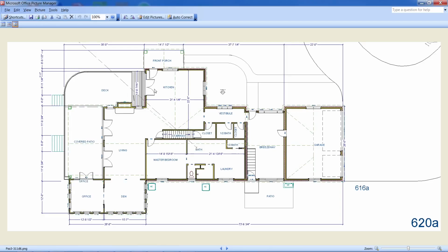I initially had you transitioning down 3 stairs to this portion here, because I have the front porch and the covered porch down 6 1/4 inches from the subfloor, which means that's going to be about a 7-inch riser there. And then I have this deck here, another 7 inches down from the covered patio, trying to get you down closer to the ground. If you had something else in mind, that all of this can be on one level. I don't believe that much was indicated on your plan. So yes, that's what I had, 1, 2, 3 to get down here, but this is really only down 14 inches from the first floor.